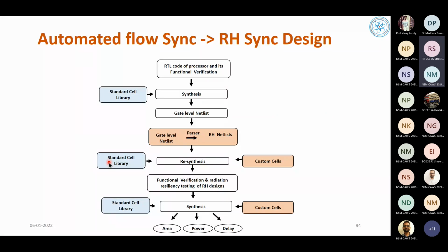Is this clear what I'm saying? Is it making sense? Yeah, so this number has to be verified. You have to be sure that your synthesis procedure is correct. So we take a design where we can count exactly how many times nodes are switching, which nodes are switching, and then we compare the numbers that we get from DC, the design compiler, with the values in the standard cell library, because these values are simply added to get the final power.